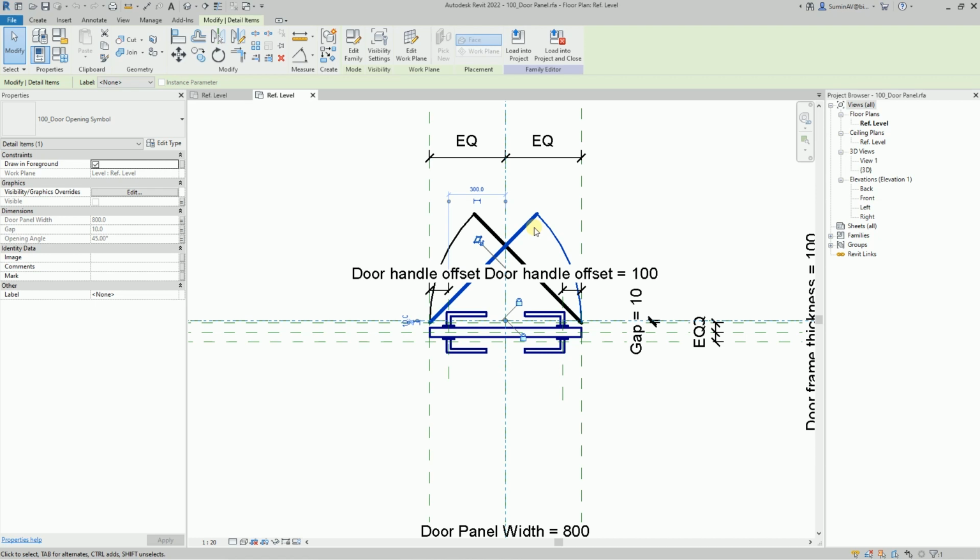If we were to create such objects directly in the parent family, we would not be able to just reflect them. We would have to reflect each line, arc, or sweep shape, and then, individually, bind them to the new position and parameterize. Revit will not do this automatically for mirrored, copied, or moved objects. We have mirrored and moved nested family instances, but they work as solid objects. We didn't have to deal with snapping each line or shape within them separately after the mirroring operation. We just snapped the entire family instance to its position.